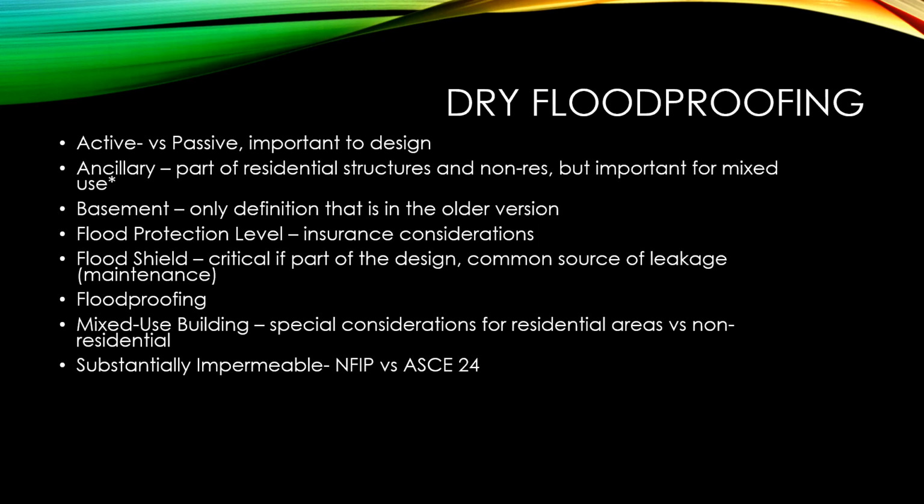So all of these things have to be complied with, and it's written into the certificate, which I'll show you. And then mixed use buildings have special considerations, and they have a section on this. Those are buildings that have both residential and non-residential uses, such as a hotel. So you can dry floodproof the non-residential sections, and then the residential ones have to be elevated.